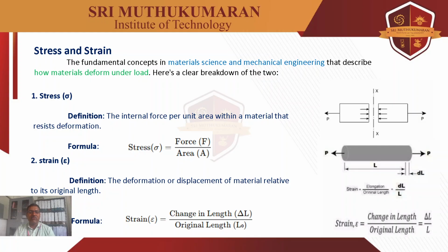Like the stress formula, stress equals force per area. The force is in Newtons. By convention for units, force is in Newtons and area is in mm, so Newton per mm square. This is the stress calculation formula.